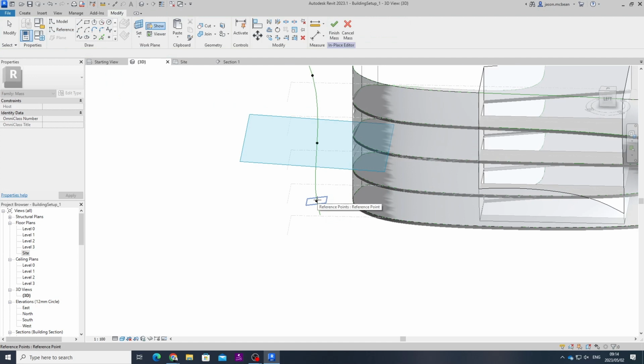It needs a form and it needs reference planes the whole time. Revit is very constrained. It needs a plane to work off. You can use other objects' faces as planes, reference lines, but it's critical to understand that Revit needs relationships with other objects. You can't just model stuff free because it's using maths the whole time. It needs something to create an equation from.